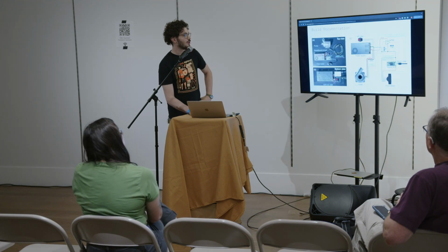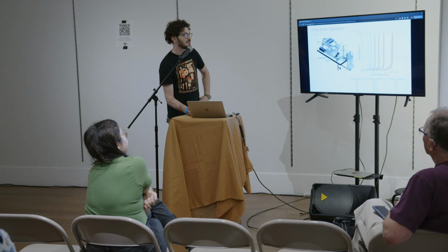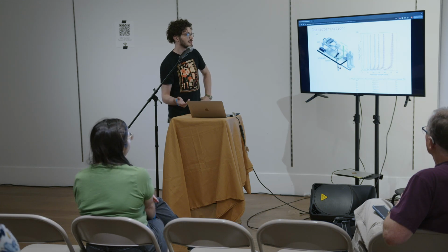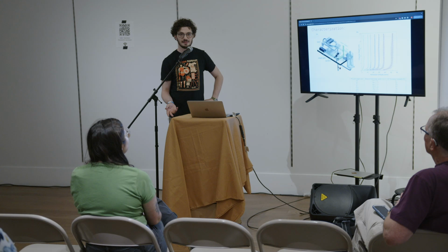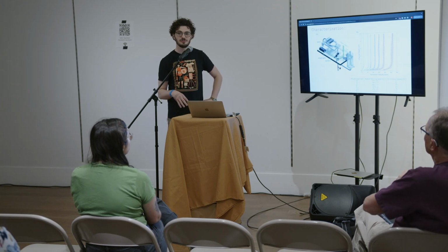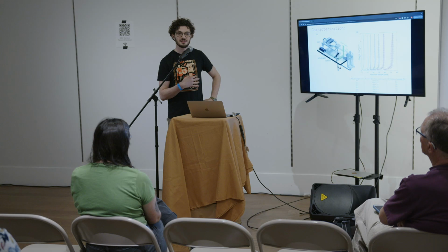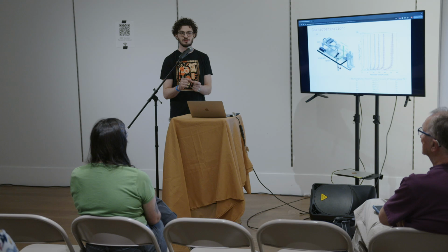Yeah. I wish I had more slides about it, but particle image velocimetry, or PIV, is a really commonly used technique in fluids. The way it works is you add tracer particles to the flow. For us, these are about 10 microns, like the size of a red blood cell, and they're hollow glass spheres that are neutrally buoyant.